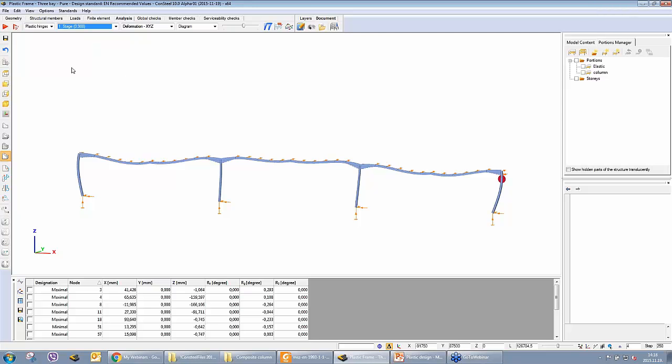It is very important to see that in ConSteel the design method is always not at the final stage, so not at the yielding mechanism, the fully plastic state. The design is not done at the 4th stage, but always the design loads are calculated, and we see what the state is at the design loads, how many plastic hinges we have under this design load level.